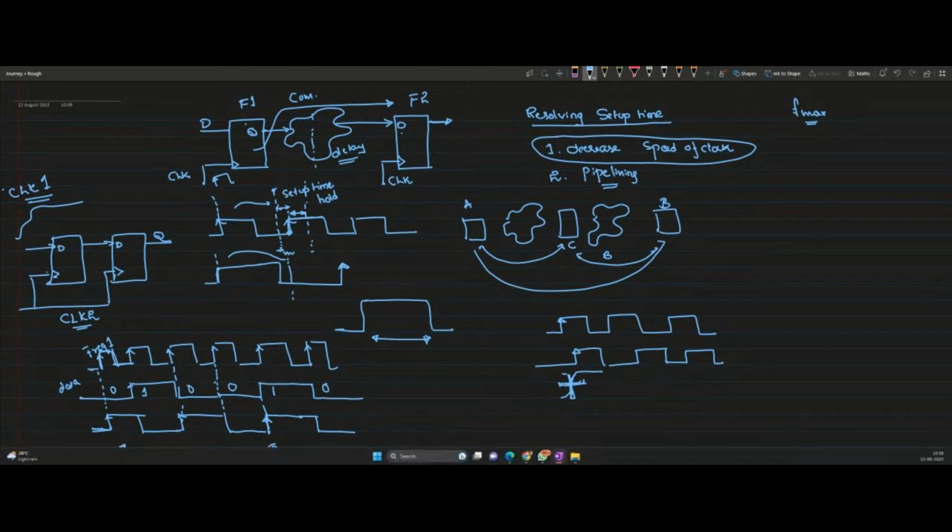This is the common issue we face in clock domain crossing. The reverse way is also possible. See what happens. This is like I'm launching the data at a faster clock and capturing at a slower clock. So in this scenario, what will happen is data loss.